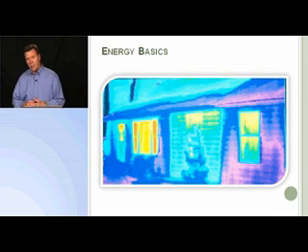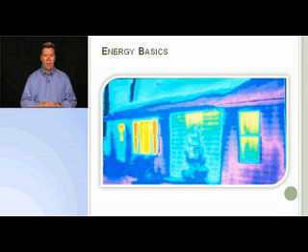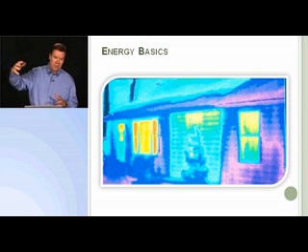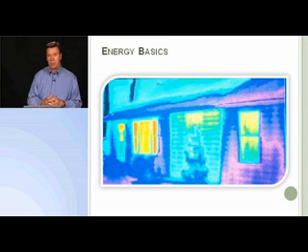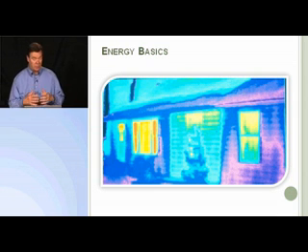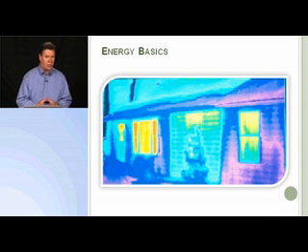And then we have heat transfer by radiation. That's why we sometimes put shade screens and things like that. We have overhangs on homes. We have low E coatings on windows to reduce that heat transfer by radiation, which is basically heat transfer from the sun radiating onto materials, and then they absorb that heat. So it's important to recognize as we select products and go through our weatherization process that we understand heat transfer so we can do a better job of making our homes more energy efficient.